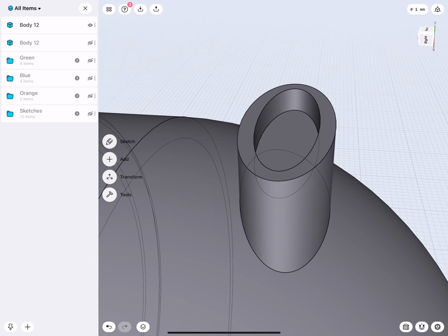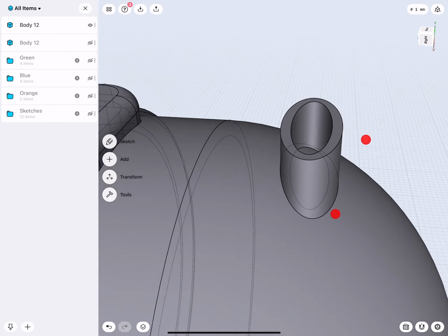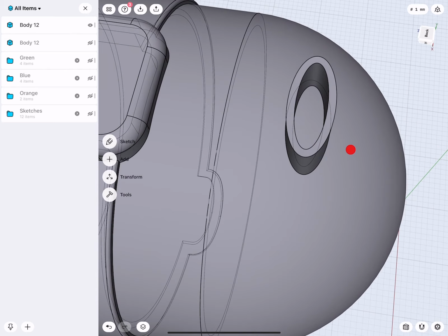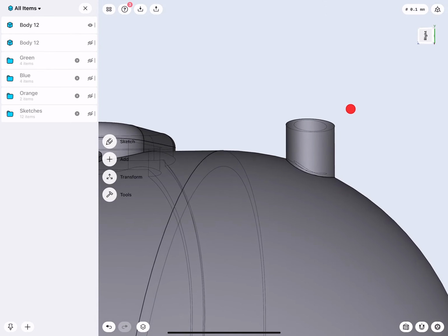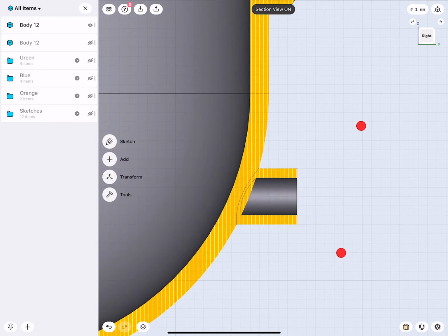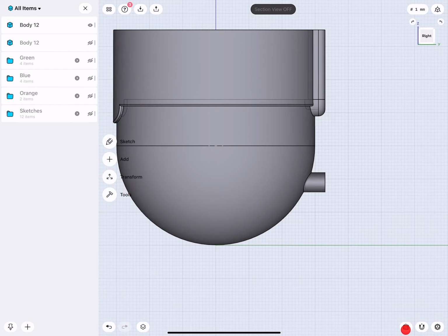So I extruded this just a little bit because now I will select this face and say replace there. Extrudes it down and matches the face. So I have also consistent material thickness. So there's nothing that is a tick thicker, as you can see. Oh, awesome. Cool. Okay.